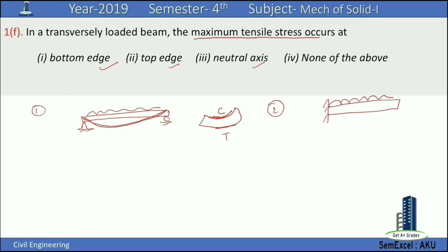If there is a transverse load, then the deflection will be like this. So there will be tension at the top and compression at the bottom. So this question is not fully right. In this question,